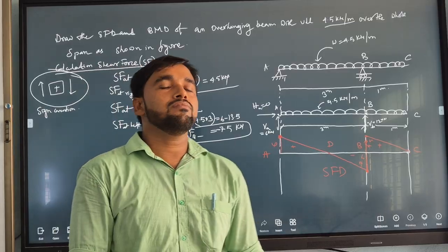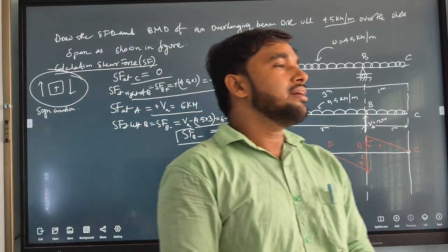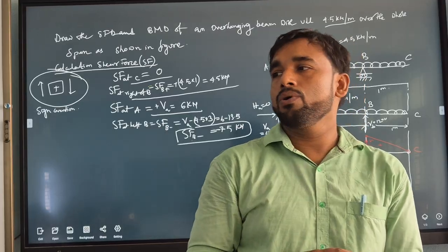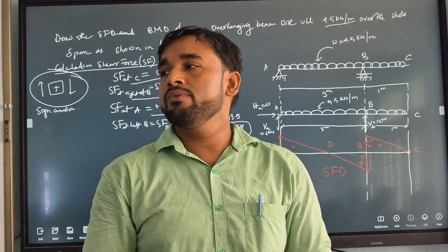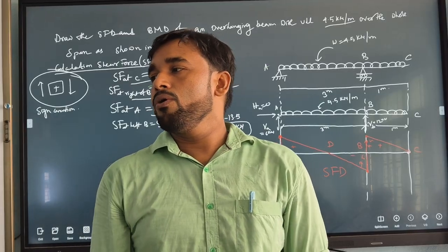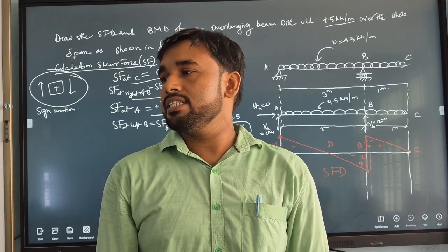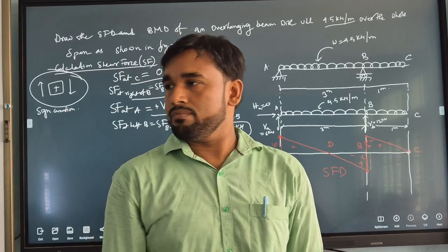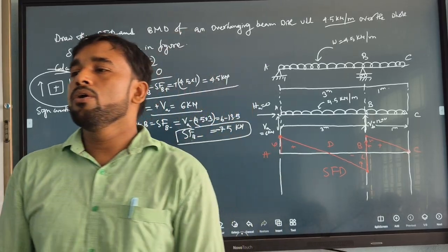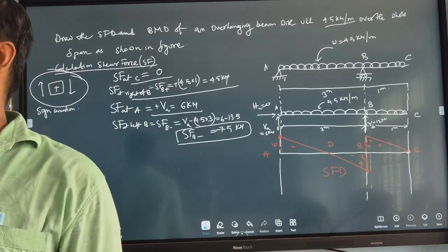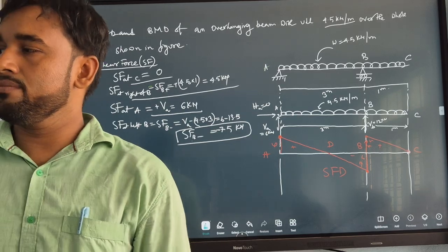Now you have to keep in mind that where shear force changes sign or shear force becomes 0, at that point bending moment will be maximum. Where shear force changes sign or becomes 0, the bending moment is maximum.